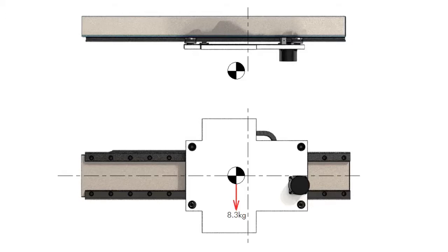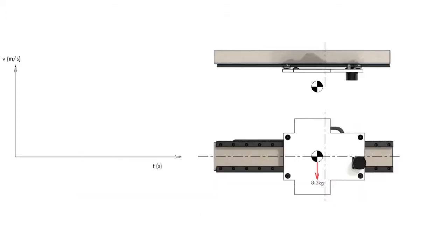Typically, these would be seen during periods of acceleration and deceleration. In a majority of the applications we see, the rate of acceleration and deceleration is relatively low. Therefore, the forces resulting from acceleration and deceleration are also low. Additionally, these forces occur for a short period of the total time the carriage is moving. In the life of the application, they make up a small portion of the load seen by the product. For this reason, we can often discount the forces that result from periods of acceleration and deceleration.